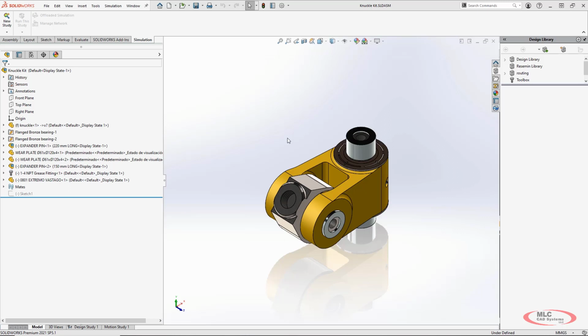So very first, when you set up a study, you can utilize the power of SOLIDWORKS CAD to set up your analysis and change your part to get ready for simulation. That's one of the powers of integrating simulation within CAD: you can easily go back and forth and set up and run studies a lot faster than any other way. For this study, we can see down the middle there is a line of symmetry. In this model, it won't make a huge difference in the solve time, but to show the process, I'll do that.